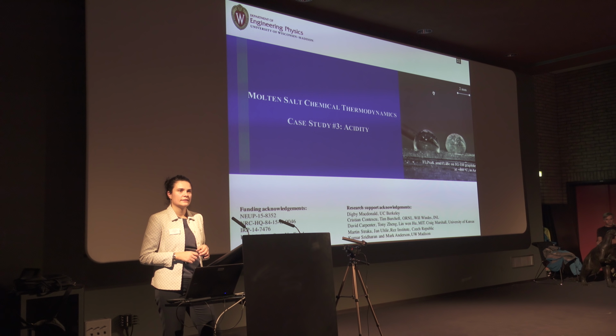You've shown that some fluorine or metals are deposited on graphite. Is that a problem in any way for a graphite molten salt reactor? It has importance for tritium uptake and also for surface properties such as lubrication and friction, and it can also have impact on the wetting behavior.